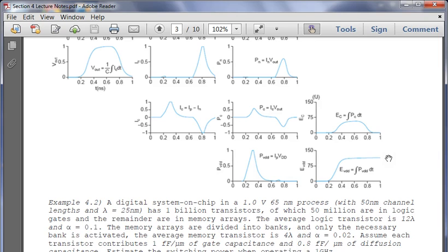When we try to reduce static power consumption versus dynamic power consumption, which is here, it's a very small amount of power. And you're going to be learning that you can use body voltage, trying to change it from 0, to be able to improve the power consumption and have it come down faster.